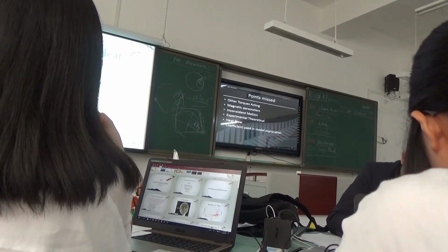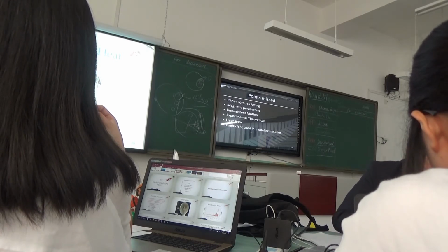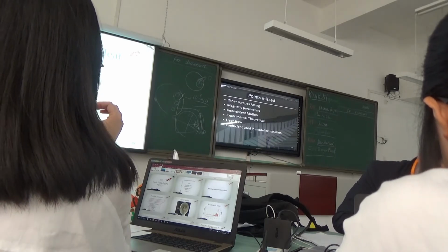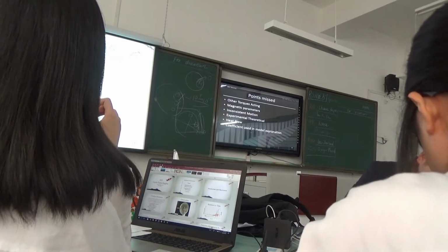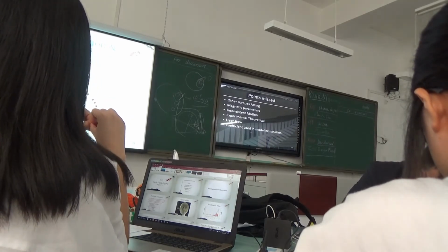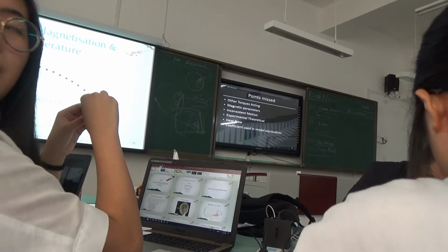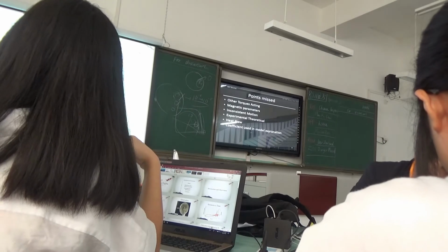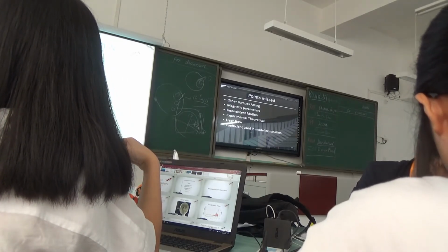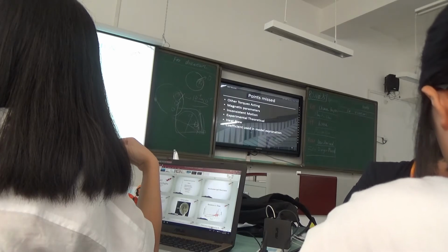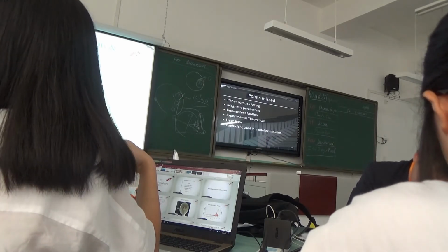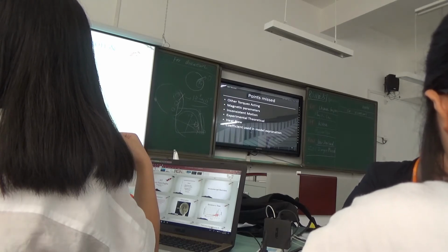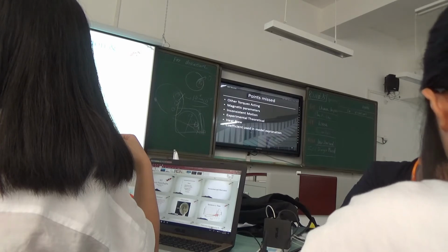And so actually measuring the magnetic field under the heat source, we can see that it stays a constant magnetic field in our experimental range of time. And then finally, this is the graph about the saturation magnetization. I want to explain once again here. We think that in our experiments, when the actual temperature of the clay is around this section, it rotates better because there is a sufficient amount of magnetization change that will cause the torque of the actual nickel disk. And that is why we don't think it will rotate better when it goes over the Curie point.